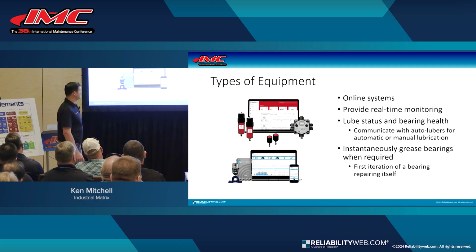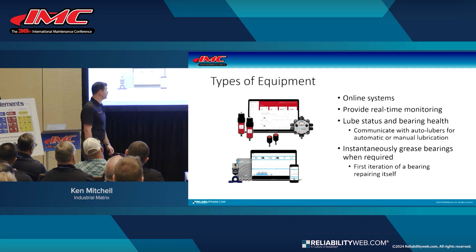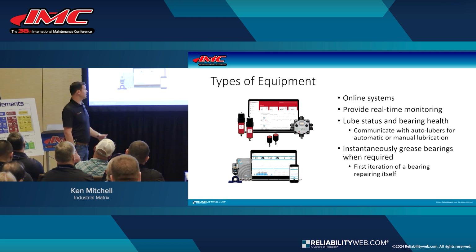And then the next generation of equipment that we're getting into is online systems. Online is definitely all the rage, putting a system out there and deploying it a little bit more hands-off. Some of the benefits: it's going to provide you with real-time monitoring, so you know exactly the health of that bearing 24/7. And you also know when it's time to grease. A lot of these start to pair up with auto lubers as well, so that bearing's continuously monitored. As you hit that threshold, your luber is going to fire, grease that bearing, and settle it back down to baseline.